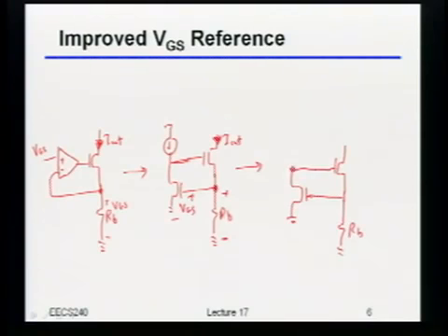And so now all I want to do is take the current that I know is going to eventually be flowing at the output and use it to give my amplifier some current. So now this is obviously completely recursive, because I needed a VGS there in the first place in order to have some current, and then once I have some current, I get that VGS. But once all that happens, indeed, this thing works. I really will have something that's set only by the VGS, and at least to first order, not by the power supply.